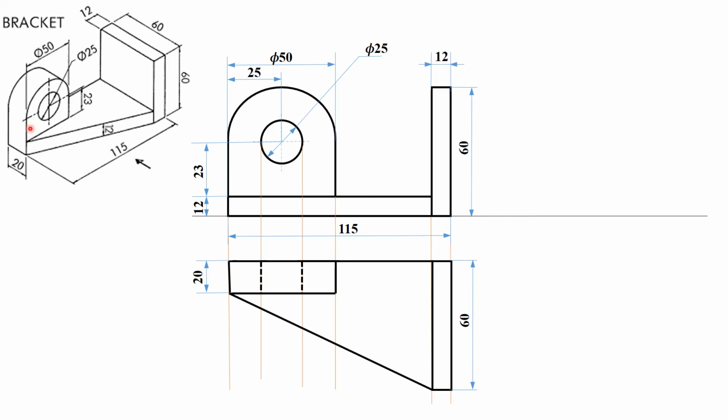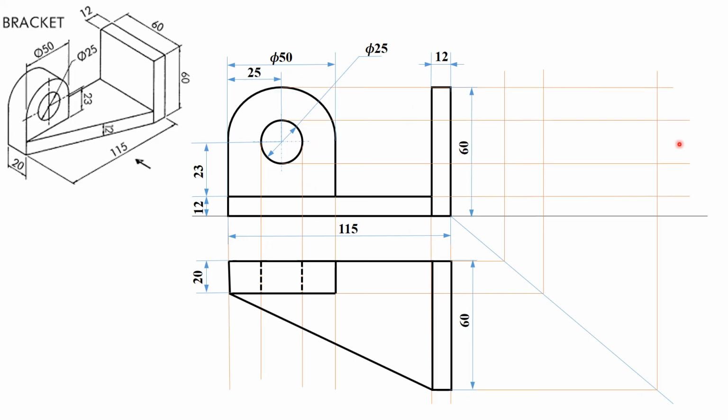Look here, when I'm drawing this surface, you can easily get it. This is the height here. Let us see how to get it. Now project all these points. Draw a line at 45 degrees with your horizontal. Project all the available lines horizontally towards this 45-degree line and project them vertically upward. Similarly, project all the available lines from your front view onto this side view. Right.